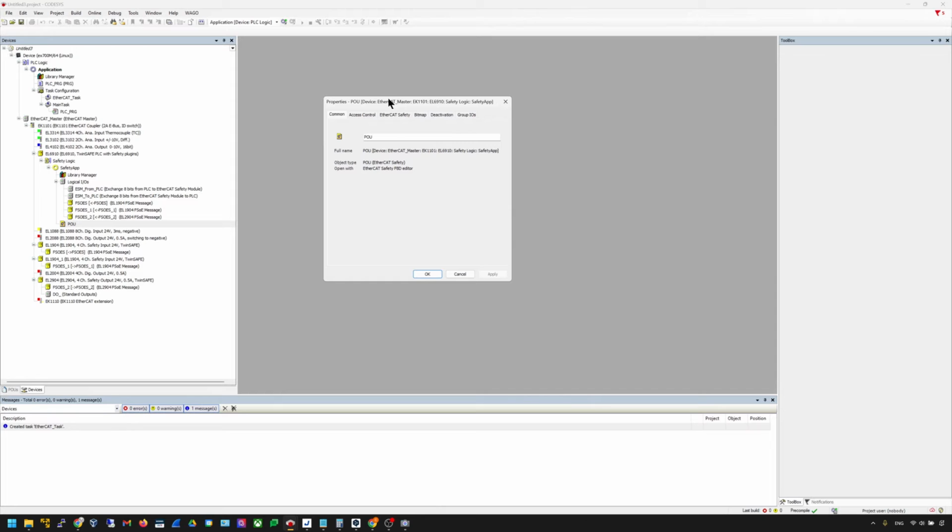properties. Then a very important thing you need to configure here is group IOs. As I mentioned before, if you watch my previous video for TwinSAFE, you know that TwinSAFE has groups of IOs that allow you to control your group logic. For example, here the input is called run stop, which allows you to trigger the execution status of your groups. For example, you need to stop the logic or run the logic. You also have an error acknowledgement to acknowledge any errors of your function or of your TwinSAFE safety group.